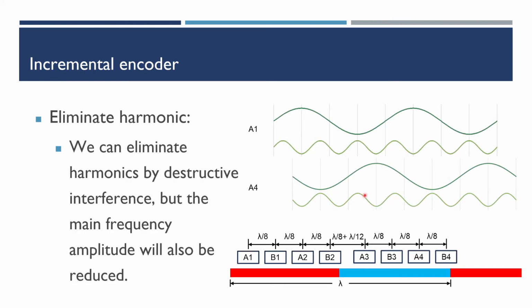So in this case, the third order harmonics can be cancelled out, and in this way, the amplitude of the fundamental frequency will also decay, but the sensor doesn't have to be operated at a large flying height. If the flying height is too high, the sensor may not be able to operate in the saturated region, since the field is not strong enough. Okay, so in terms of the accuracy, the position error will be in the form of a sinusoidal wave with the effect of harmonics.